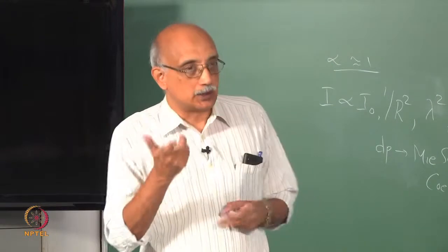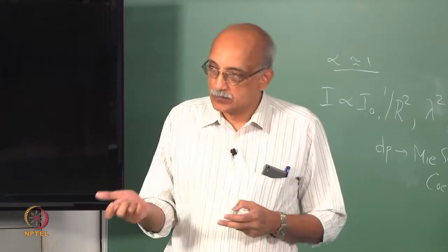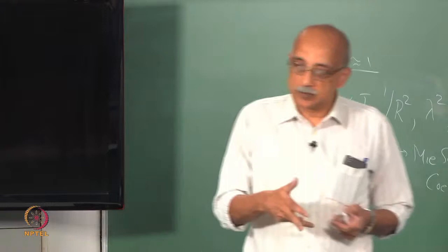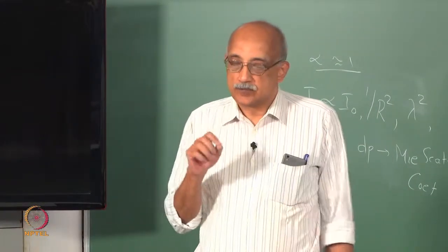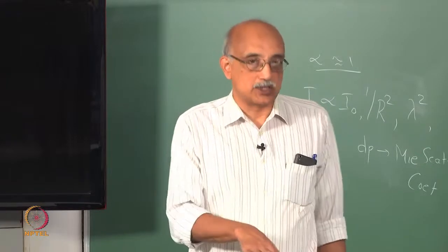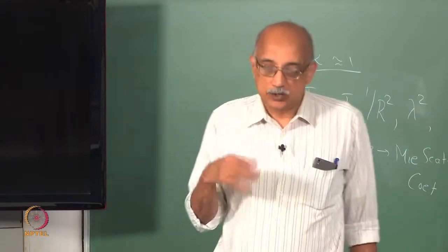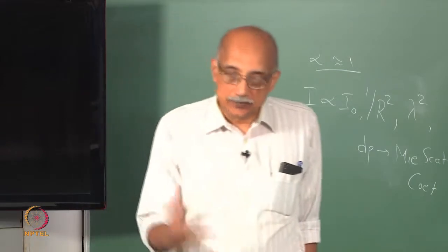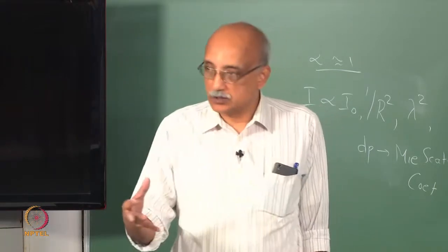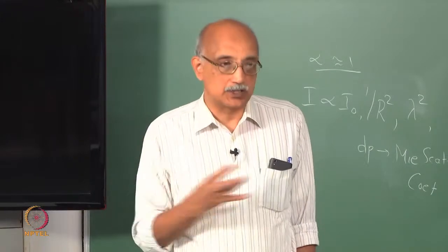Okay. So, it does both, it gives you count as well as size, but the limitation of the method is because of the way it does the counting and sizing, you really cannot go down to nano dimensions. So, if you want to use a particle counter for nano suspensions, you really have to have a way again of growing the particles to a larger size and then measuring them.